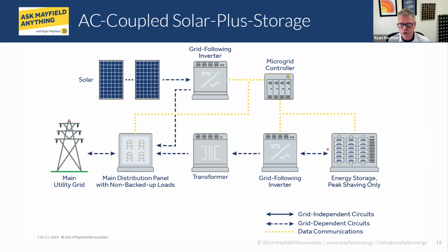And the need for a transformer, I guess Medina and Nick and Jeff and Blair, I'll throw this at all of you, the need for that transformer in this grid following case versus, in the next slide, grid forming, where the battery inverter is forming the sine wave and powering up backup loads. Is that a big differentiator in your eyes? Maybe I'll look at Medina and Dynapower first. This grid following versus grid forming and that transformer requirement.